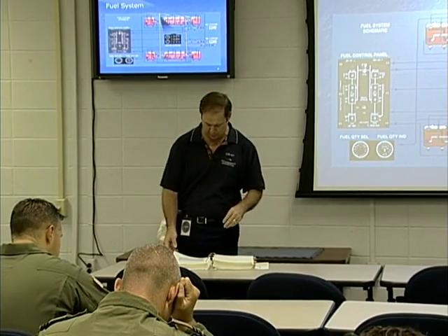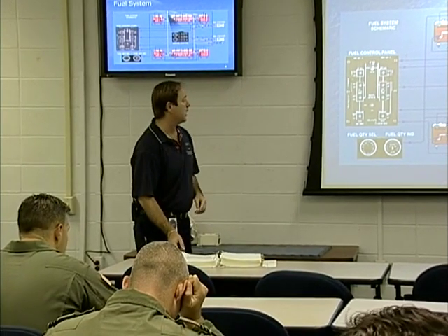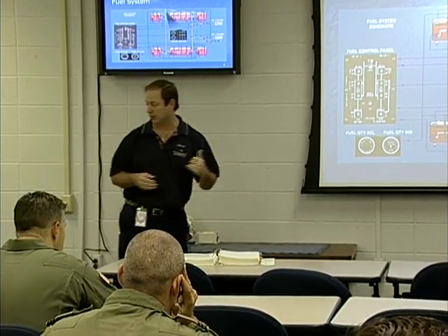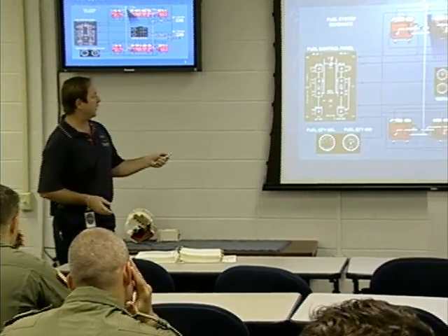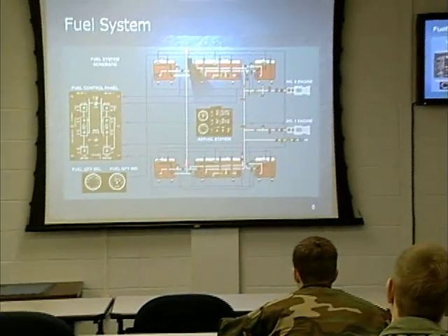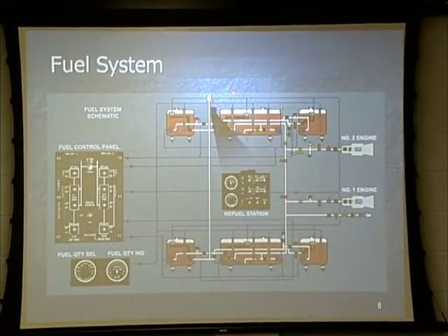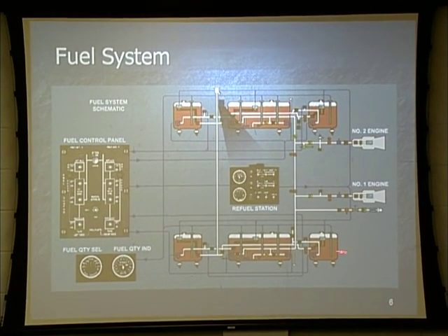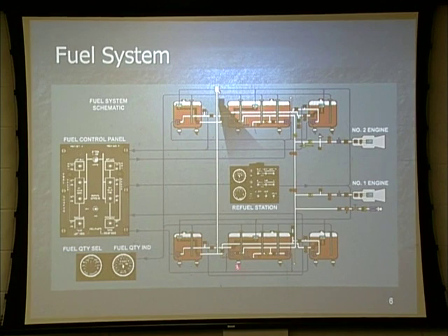The heater, we already talked about that, 2 separate connections for the cross feed and the transference of fuel during refueling operation from the right side of the aircraft to the left side of the aircraft. So we have this line right here, which is going to be used to transfer fuel through the D1 receptacle to both the right side tanks and over to the left side tanks. That's all that line's allowing for, which means this line is only going to be used during what operation? Refueling operation.